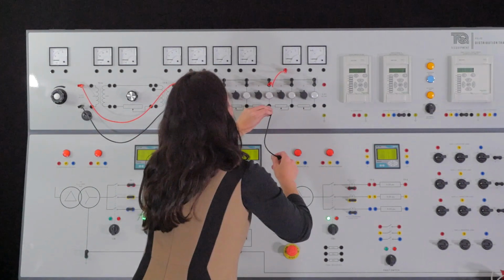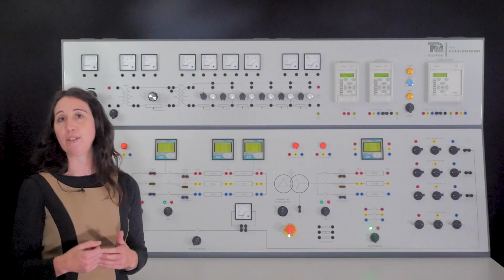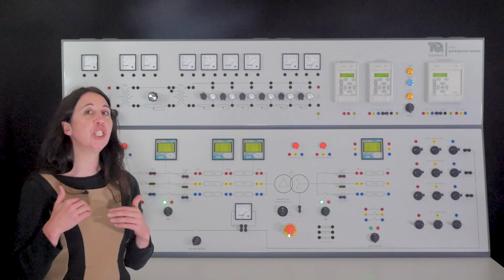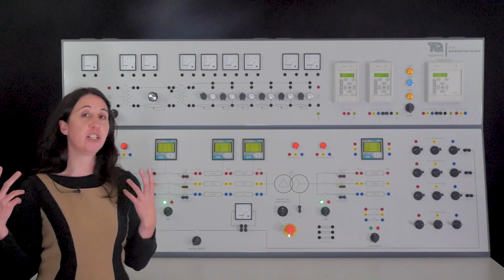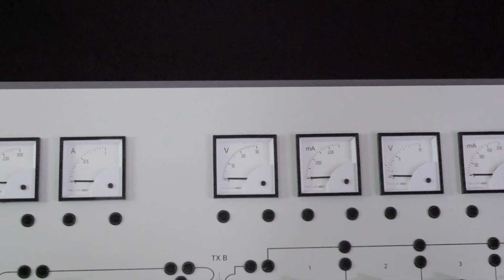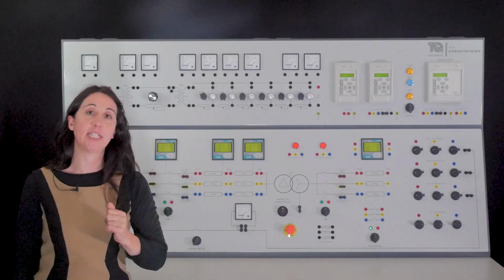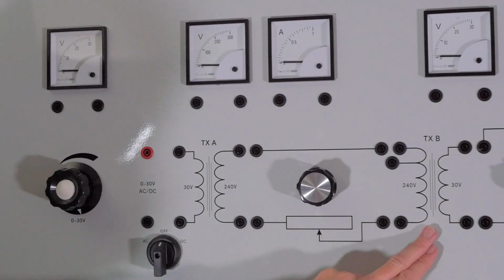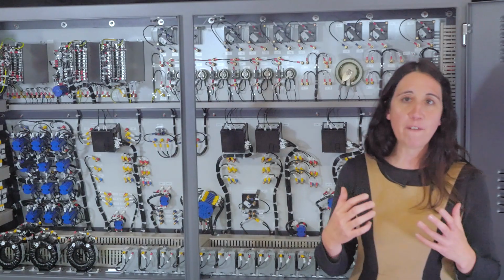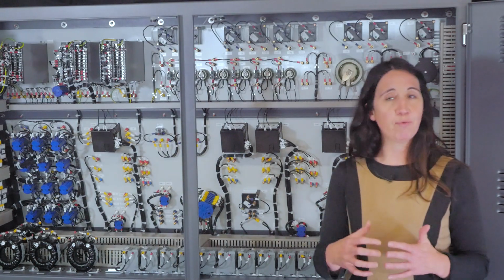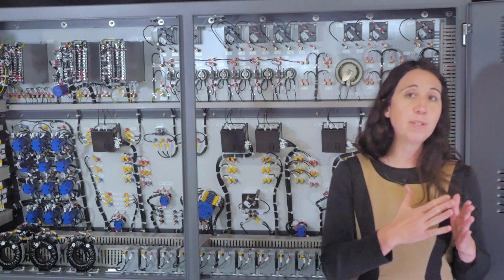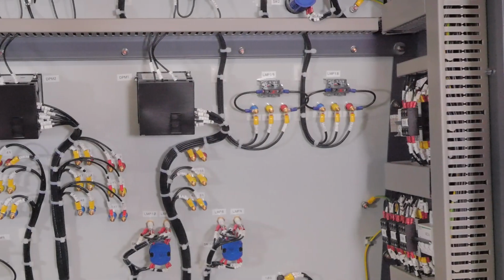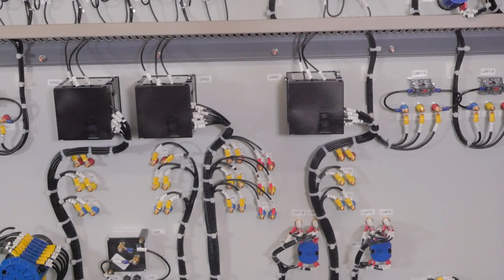Using this simple model, students get to grips with the fundamentals of a distribution system, allowing them to begin to understand what factors influence the volt at the consumer and how this voltage can be controlled. 9 analog meters are provided to allow quantitative analysis of the effects observed. 2 simple transformers are provided, one step up and one step down, linked by another section of feeder, whose resistance can be changed to represent different lengths of cable between the substation and the first consumer. Power to this section is from a variable source that can provide either low voltage AC or DC.